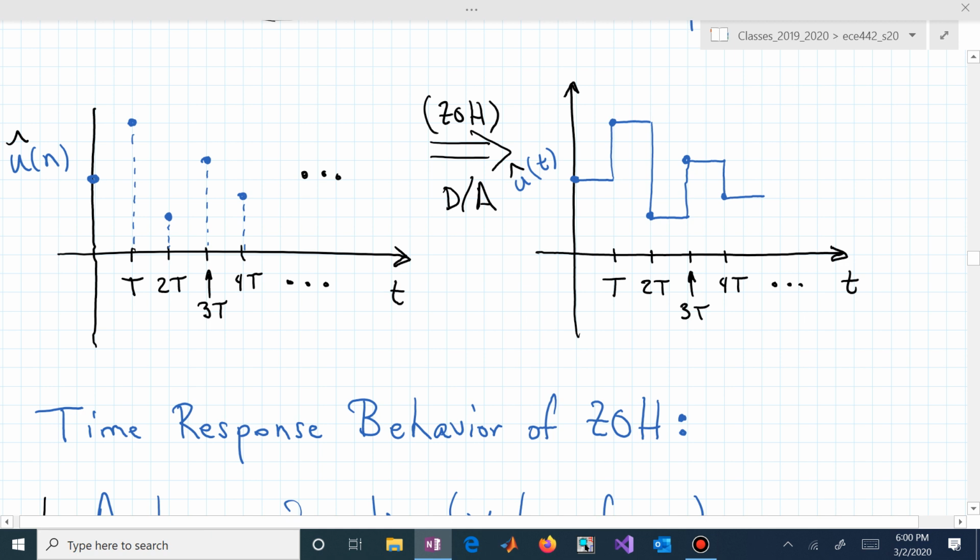So for us, we are choosing the zero order hold, one, because it's probably the most straightforward to analyze, and it's not necessarily going to damage us too much. It basically introduces a little lag into our system response. And if you've had a control class in the past, you know that lag is not good.